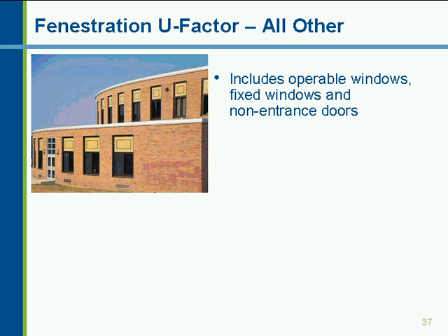Now, I do want to say that even though the U-factor requirements on this type of fenestration for all of these categories varies based on the type, the solar heat gain coefficient requirements are going to be the same from category to category. So if it's a 0.40 for one type of glass, it's a 0.40 for all glass in that particular climate zone.